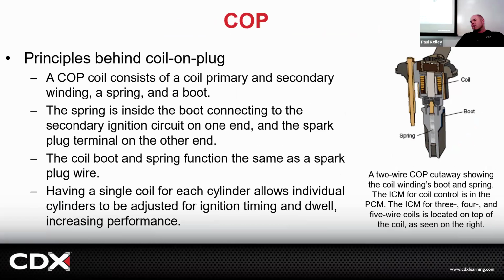You couldn't even see it. The thing is you could scope it, but you'd actually scope the photodiode, and by the time it's behind the water pump, we're not really. A lot of times we're just like, you know what? You need a new OptiSpark distributor because it was so hard to really even test this system.